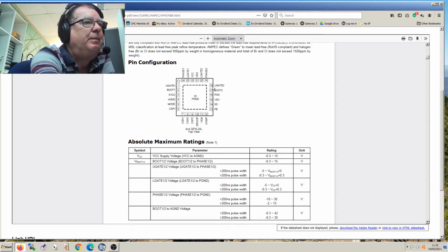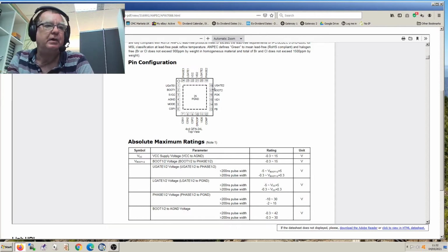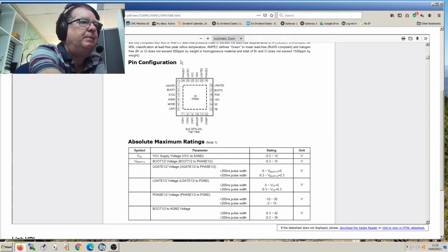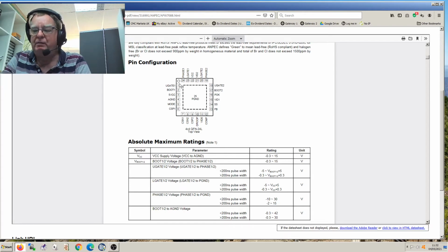And I can see that from pin 18, I've got a connection to that end of the missing resistor. So what I'm going to do now is tag my wire on the gate of the other upper side MOSFET and measure the resistance from there to pin 1, and that will tell me the resistance of that missing resistor. Well, it's not missing, I've got it, but it'll tell me if it really is 0 ohms or that component's faulty.